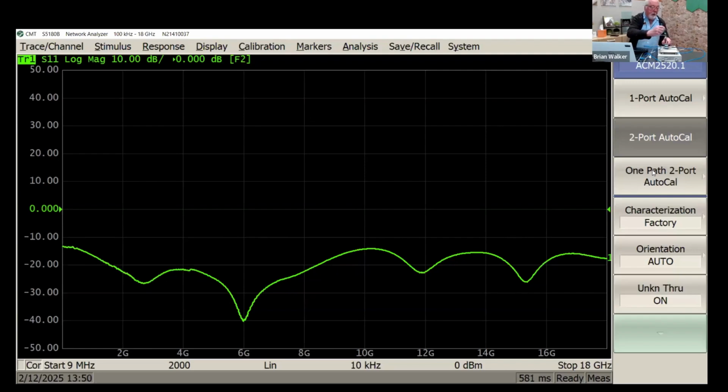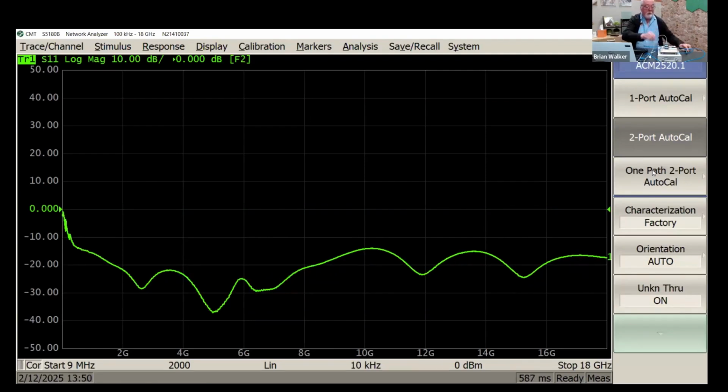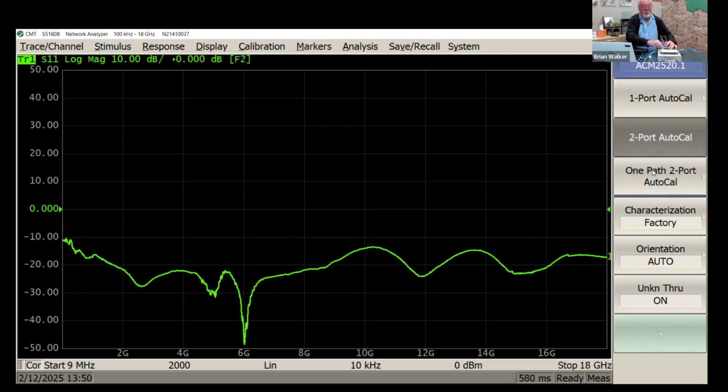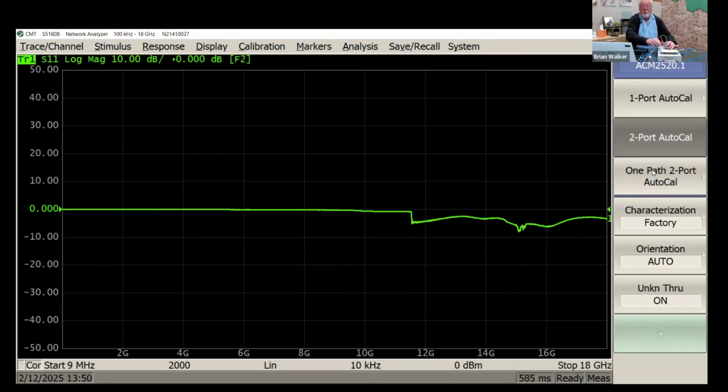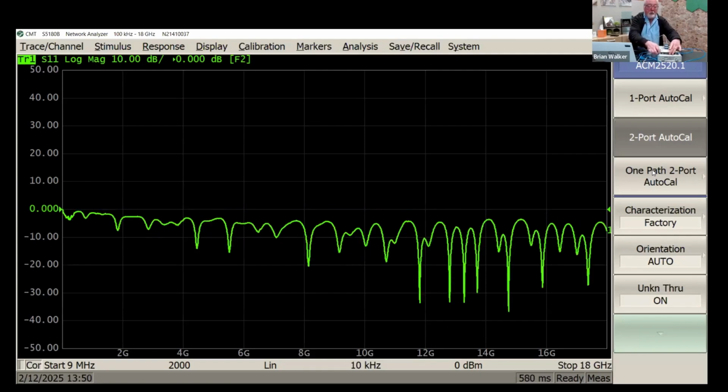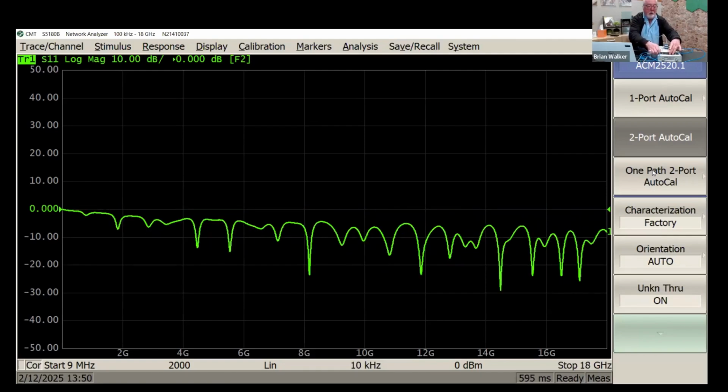So if you do have a VNA, you will want to have an automatic calibration module. It greatly simplifies the calibration process, eliminating many errors that you might otherwise create. And it gives you superior calibration compared to a mechanical calibration kit. The artifacts inside the automatic calibration, that's the load, open, short, and through, are data-based.